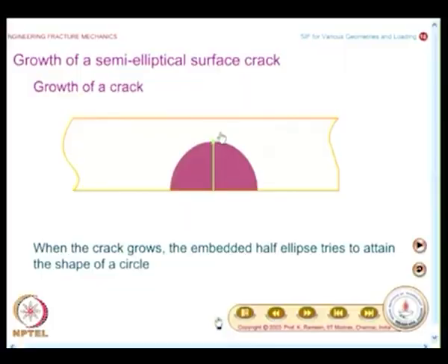However, you could also have crack propagated because of a water hammer. In that case, the pressure would be higher than the original pressure. So, when you are designing, you have to ensure both the possibilities, pressure coming down or pressure going up also. Pressure going up has to be looked at much more carefully. And another aspect also you can learn from this. If you go and look at the literature, we would also discuss about this towards the end of this class.